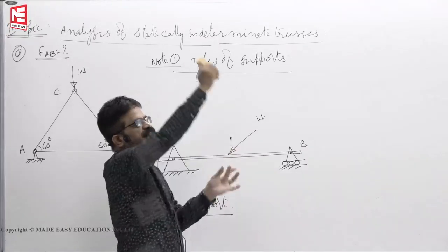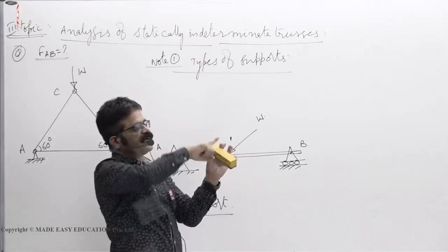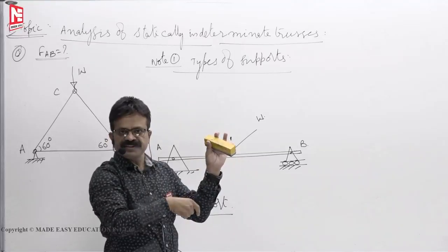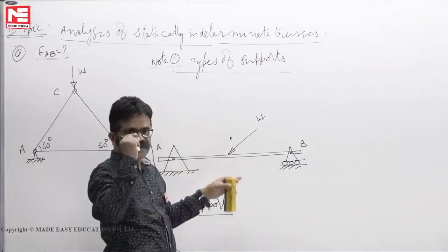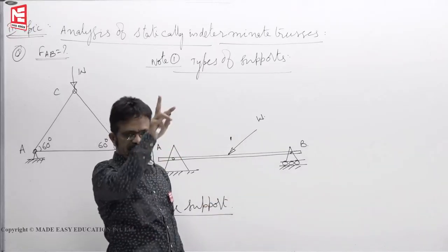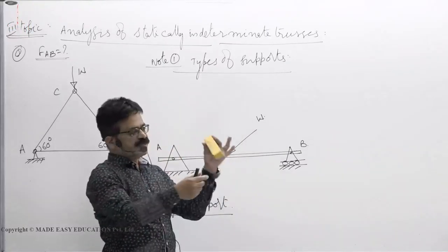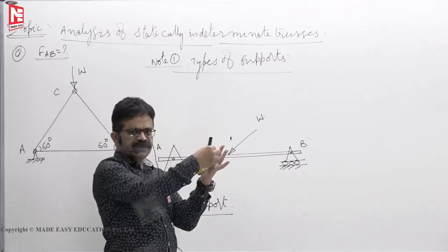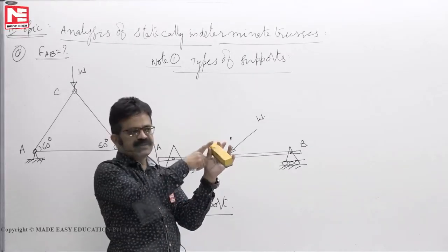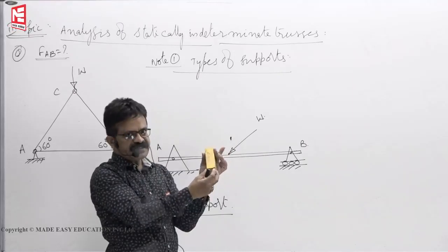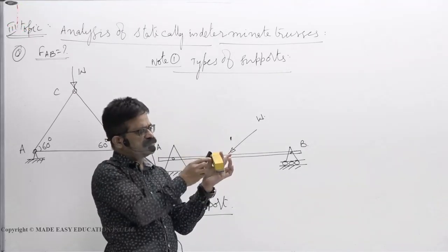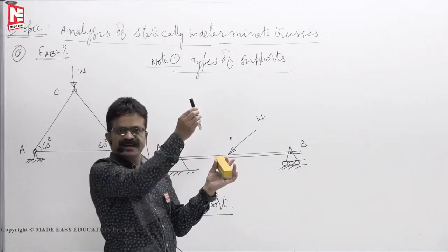Now if you try to lift it up, it will not go up. Again there also it is subjected to double shear. So pin can offer horizontal reaction, vertical reaction. Now however hard you tighten the nut, single force only, two forces are there like this. If I try to rotate like this, those two forces, resultant force will form only a single line.